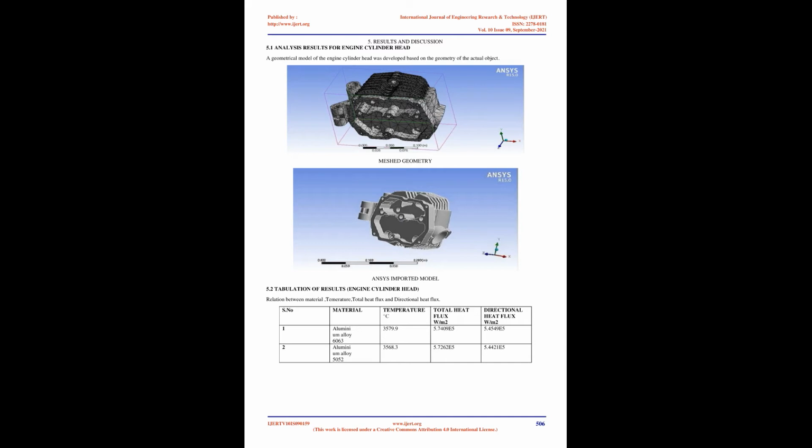A 6-stroke engine describes a number of different approaches in the internal combustion engine to capture the waste heat from the 4-stroke Otto cycle and use it to power an additional power and exhaust stroke of the piston. Designs either use steam or air as the working fluid for the additional power stroke. As well as extracting power, the additional stroke cools the engine and removes the need for a cooling system, making the engine lighter and giving 40% increased efficiency over the Otto cycle.